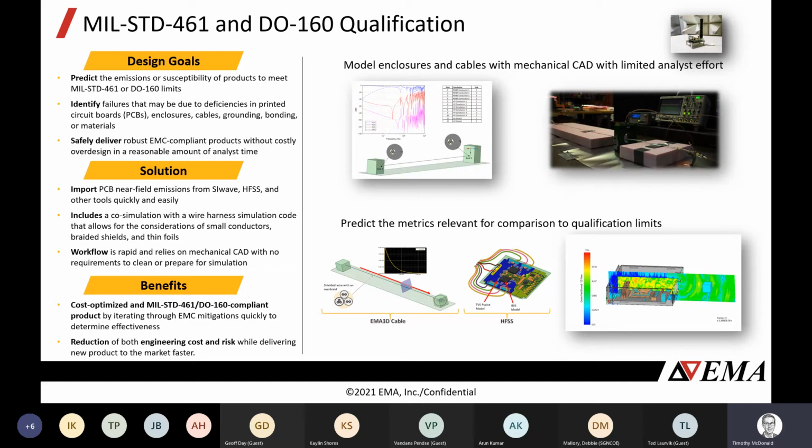Okay, there's other environments, and we have to consider more than just the full aircraft. Typically, we're flowing those lightning and HIRF levels to the units. As well, the units have all the usual EMC requirements, radiated emissions, radiated susceptibility, etc. Those usually manifest itself for the tier 1 suppliers as either MIL-STD-461 requirement, which is a unit level requirement in aerospace for electronics suppliers, or DO-160, which is a civilian set of requirements, many of which are electromagnetic in nature.